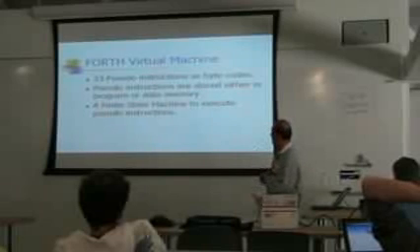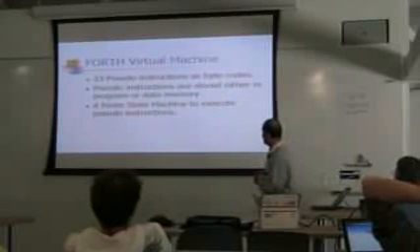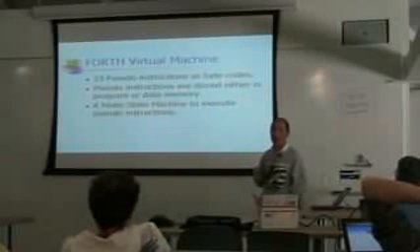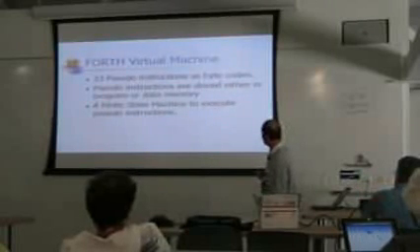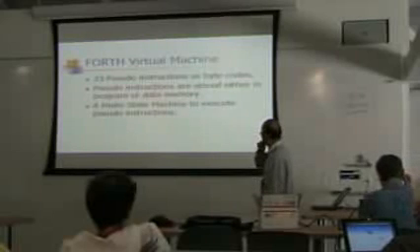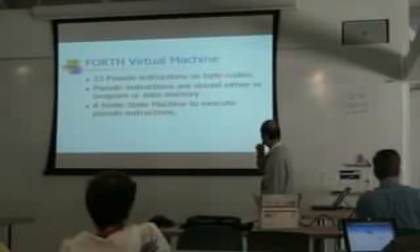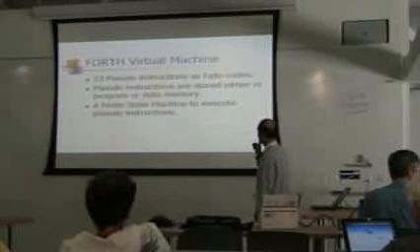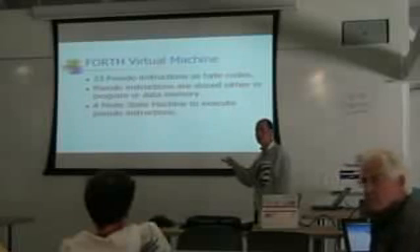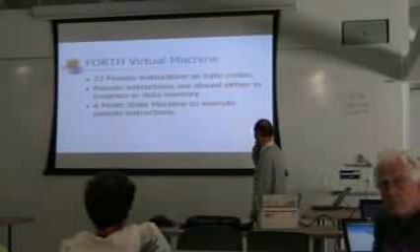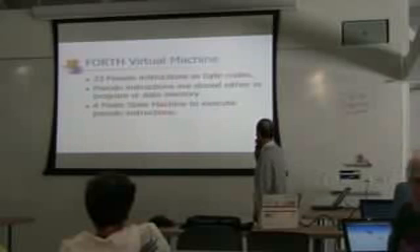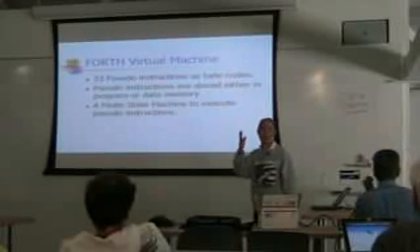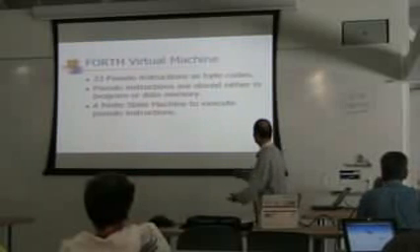These are the machine instructions for the eForth virtual machine. When we designed the EP32, we designed these as actual machine instructions. But here, in a virtual machine, we use pseudo instructions, and pseudo instructions can be stored in program space or in data space. It is bytecode, okay? Actually, we only need 5 bits, but we give it a byte anyway.